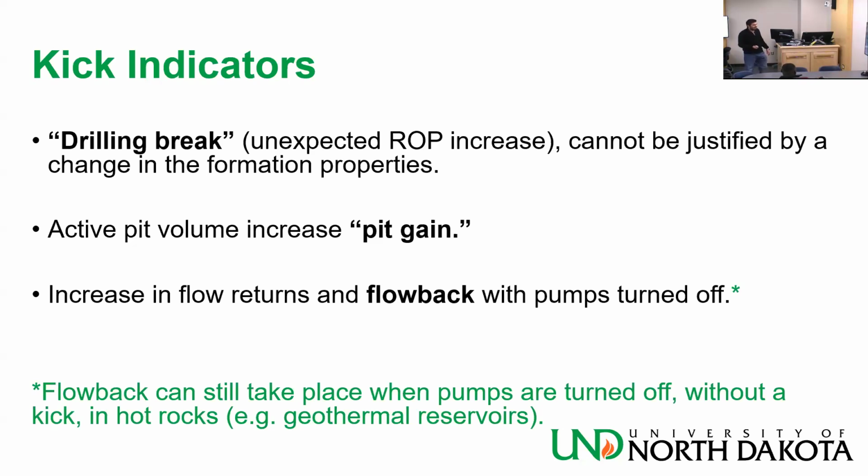There is an exception to that, and that is if you are drilling through a hot rock. When you stop pumping, the hot rock heats up the mud. The mud expands and creates a flowback. It creates a flowback not because the mud was the wrong density, but because the formation was hot. But if you keep doing it, when it expands, what happens to the density?